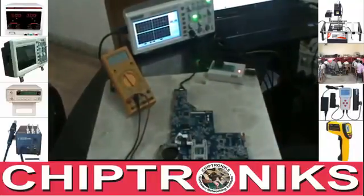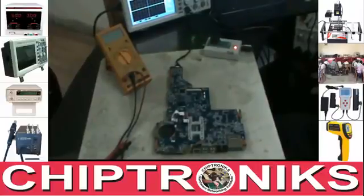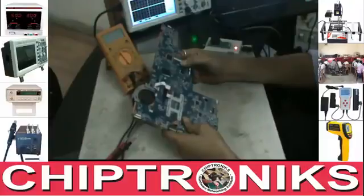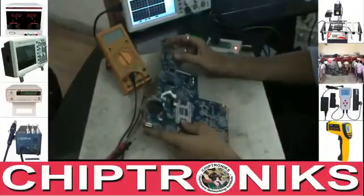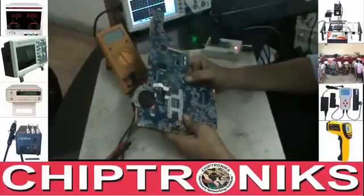Some kinds of motherboard have a PCH IC. It has two BIOS ICs: one is the EC BIOS and the second is the system BIOS. The EC BIOS always connects with the IO IC, and the system BIOS connects with the PCH. The EC BIOS is the embedded controller, which controls your IO, and the system BIOS is for display only. That's why if your motherboard is in dead condition or has a charging problem, and you need to work on it, if the problem is in the BIOS, you need to work on the EC BIOS, not the system BIOS. Okay.